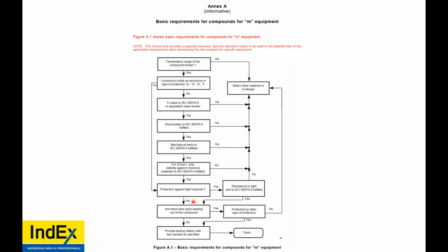Does it need to be protected against light? Yes or no? Yes. Has to be resistant to light to tests identified in -0? No. Are there bare conductors? Yes. Protected by another EX protection technique. So I showed you those bus ducts. The end termination is bare. So they had to be inside of an EXE enclosure for that transformer terminations. If no, provide test sampling. Then it goes to the EXTL for testing. If it passes, it goes to the EXCB and they write the certificate.